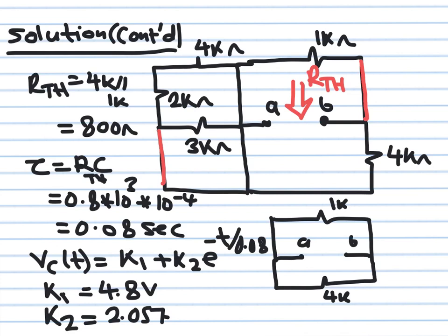Okay, so the last step in my calculation, I removed this independent source here. So this voltage source is shorted, this voltage source is shorted. This is now how my circuit looks like. Notice that this short circuit here will get rid of 3K. And if you have a short circuit here as well, you will see that also this 4K and 2K have been shorted as well, because you can see this is all one point now. So what you really have is only point A connected to 1K and another 4K on the other side. This is how really the circuit looks like.